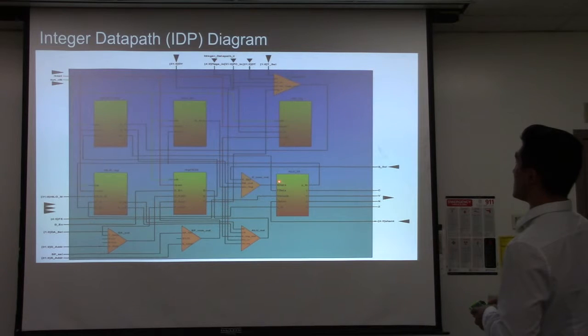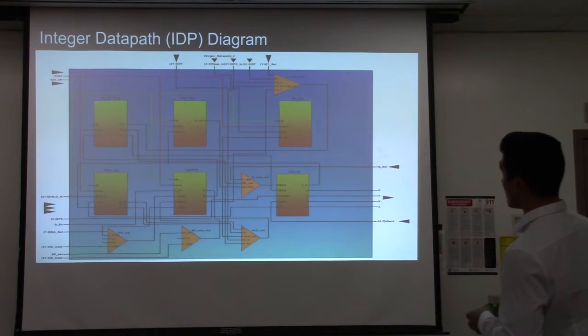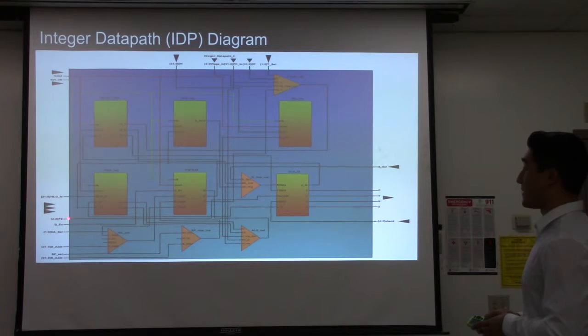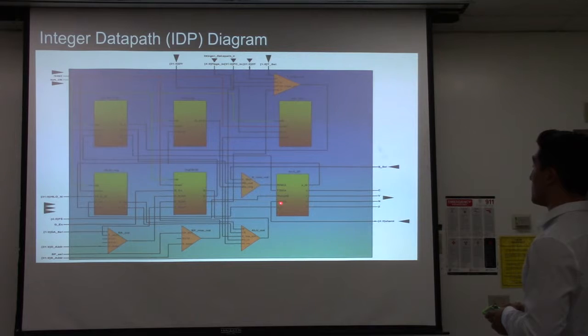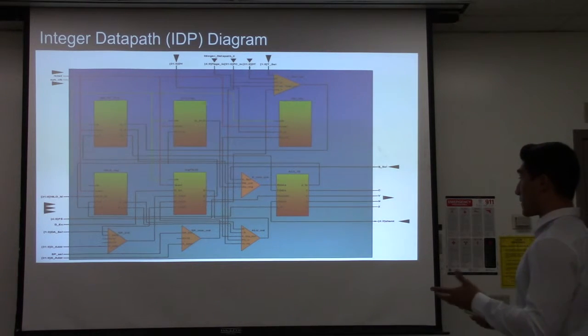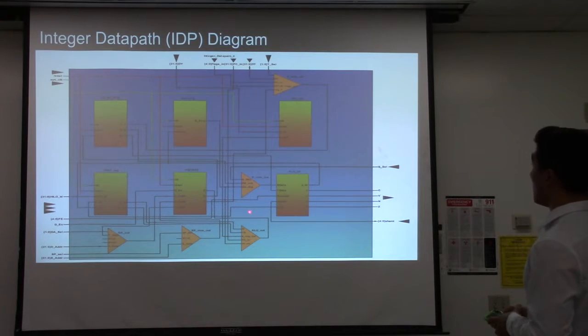And our ALU takes in the data as the S data, the T data. This does most of our computations. We get our opcode from our 5-bit FS signal from outside. We also have a shift amount input from outside, if it's a shift arithmetic or a shift logical. We have our C, V, and Z flags, which come out of the ALU, which are just our status bit flags.